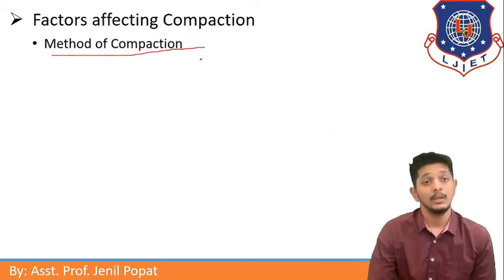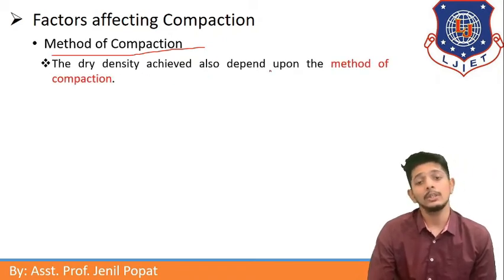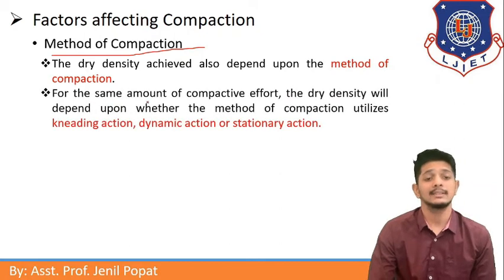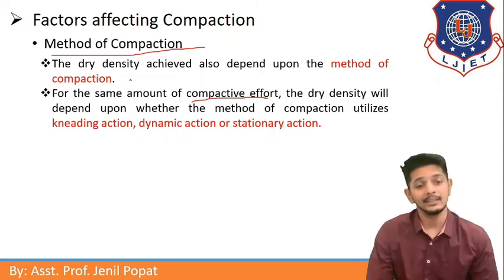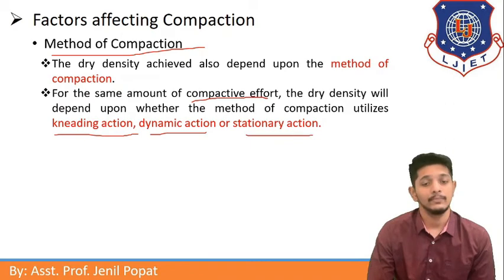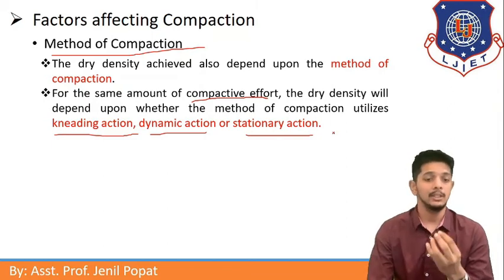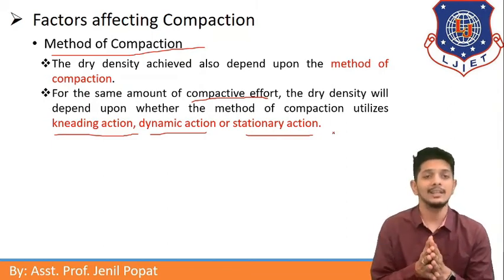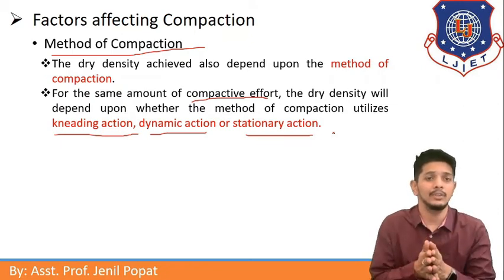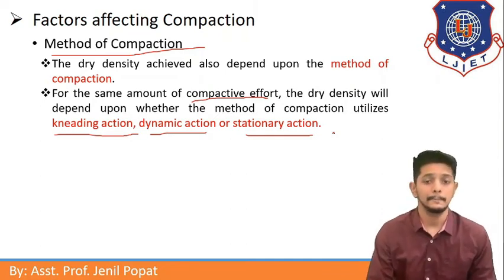Method of compaction. Which method you are adopting is also important here. The dry density achieved also depends upon the method of compaction. If you are applying the same compactive effort, the dry density will depend upon whether the method of compaction utilizes kneading action, dynamic action or stationary action. Stationary action means static action. Dynamic action means it is moving, and kneading action means it is vibrating kind of thing. It is making particles alive. Let us move further.